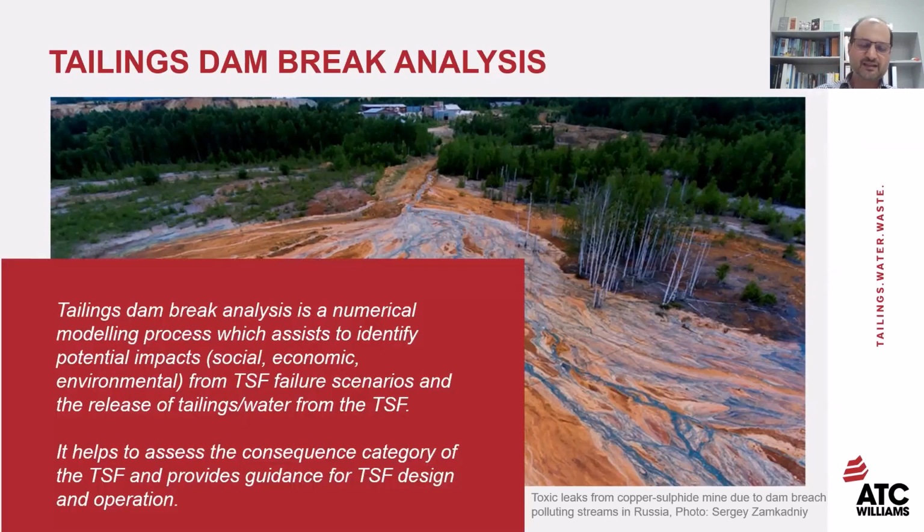Tailings dam break analysis is a numerical modeling process which assists to identify potential impacts, social, economic, environmental, from TSF failure scenarios and release of tailings and water from the TSF. The analysis will help to assess the consequence category of the TSF and provide guidance for TSF design, approach and operation.